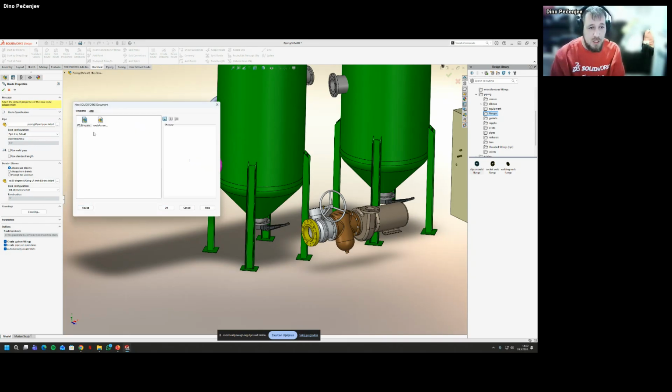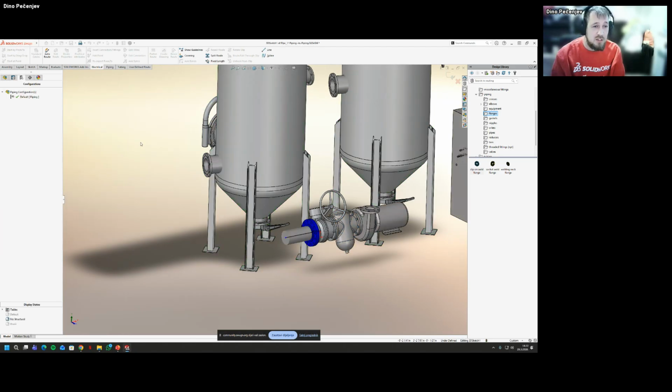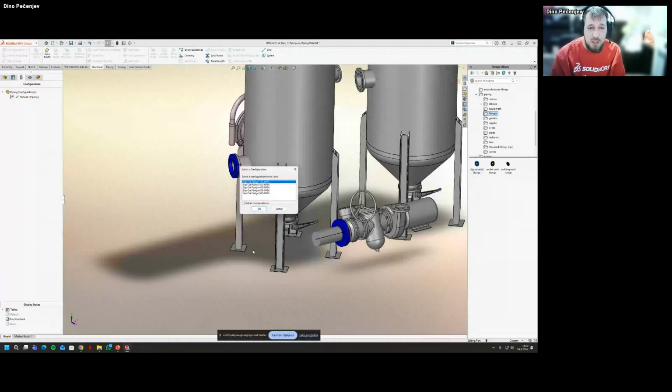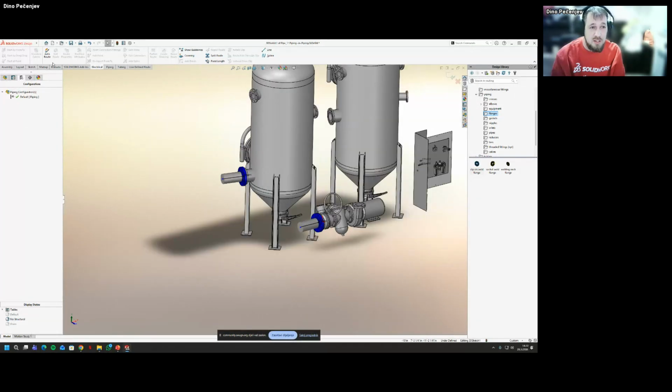So regarding the template, I'm going to set feet, inches template. I've set, and I'm ready to go. I'm just going to drop here another flange with the same size, use auto route, and just to notice here in the command manager, you have 4 different sections.